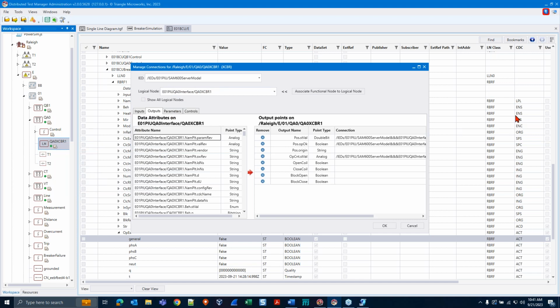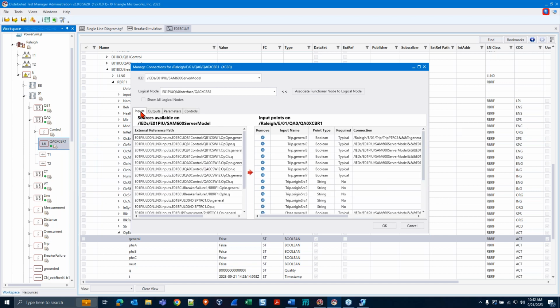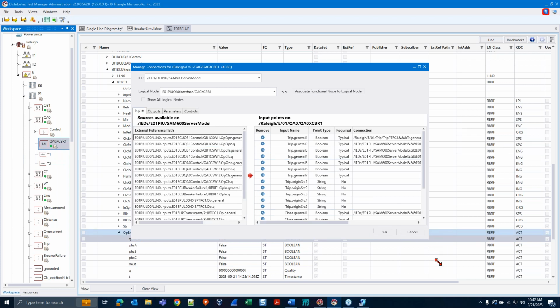So we're getting closer. We've now linked our substation section down to our IEDs, but now it's time to link the communications that are flowing between our different IEDs. So those GOOSE messages, all important GOOSE that replaces wire, signals that go between different IEDs. And we now need to link them up to our functional nodes up here, or LNs up in the substation section. So to do that, or to see how that was done, I'm going to come over here to my input section. So for this XCBR, we've defined a couple different inputs that we think a typical XCBR might have.